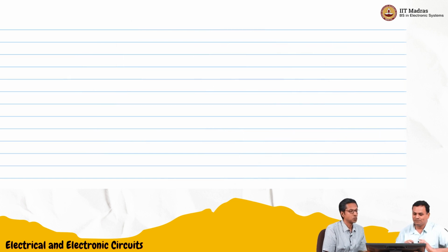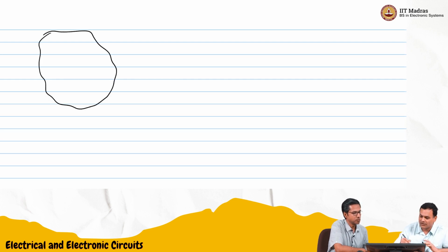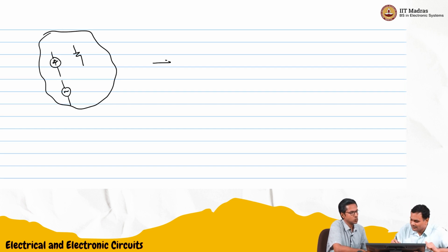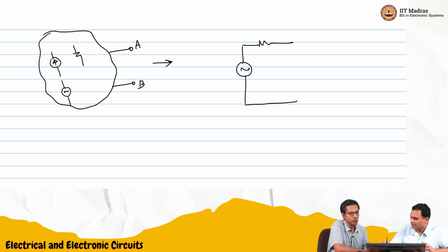Now our definition, I think we started off with some network. We said the network can have current sources, voltage sources, and here we can have AC current sources, AC voltage sources, and resistors. We'll start with this most basic definition. Then you can have a Thevenin equivalent across two nodes, A and B. There will be a single pair of VTH and RTH. This is the most basic form of the AC.